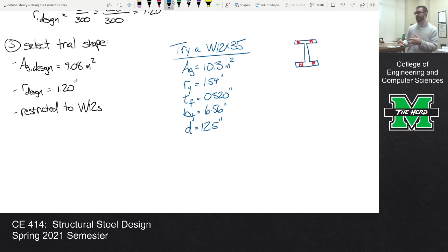The fractional values are what you would use for drafting and detailing. So if you were drawing this out in AutoCAD or MicroStation or whatnot, you would use the fractional values. The decimal values are what we use for design. And in design, we always use the decimal values. So just to use the depth, for instance, we're always going with the column on the left, not the one on the right.